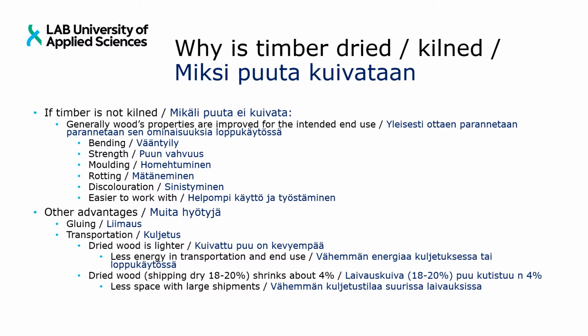But also it's important that timber is usually easier to work with when it's been kiln dried. There's one exception: thermally modified timber, heat treated timber. Actually, it gets so strong that, for instance, if you want to put a drill into it, you need to drill the hole first before you put a screw in there.